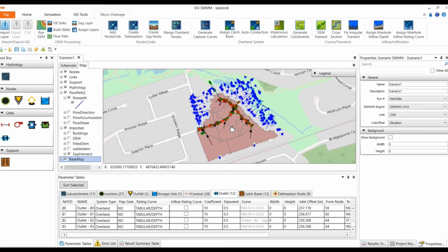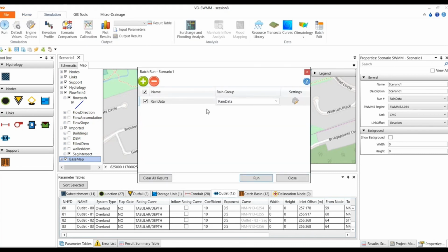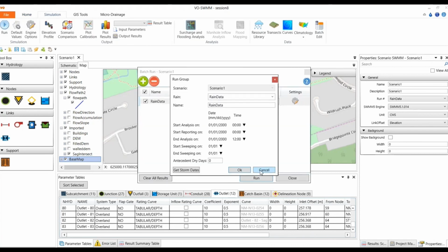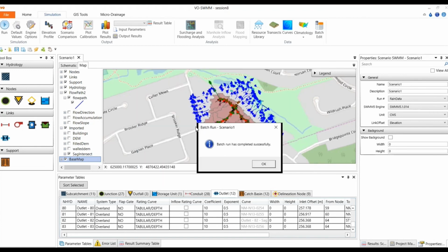system. And also all I need to do right now is add the rainfall data, which I already did, and then run the model to see how much flow is going to be generated, and then how much water is going to flow into my sanitary or my storm system. So all I need to do is run my model. And in order to do that, we're going to go to the simulation, run. That was the same thing because I ran the model, and we'll click on run.